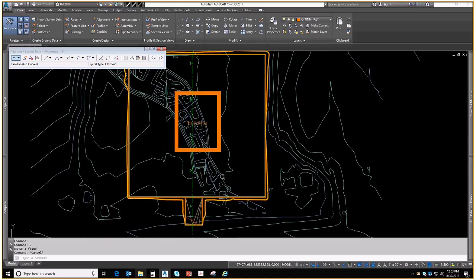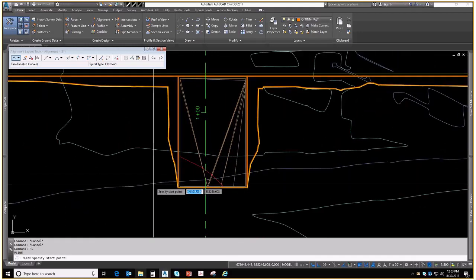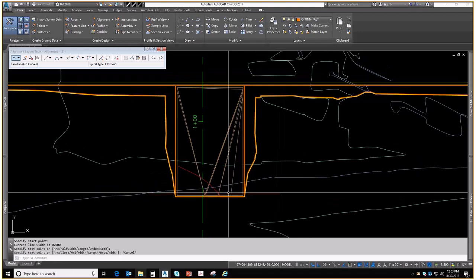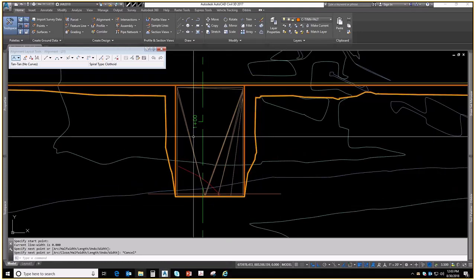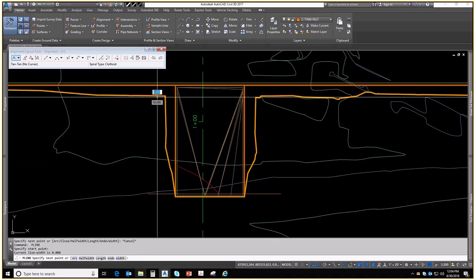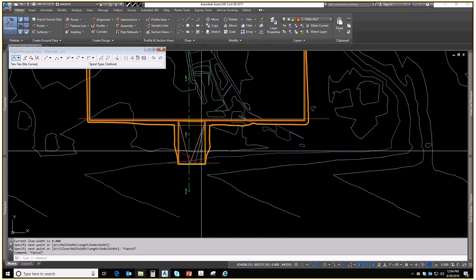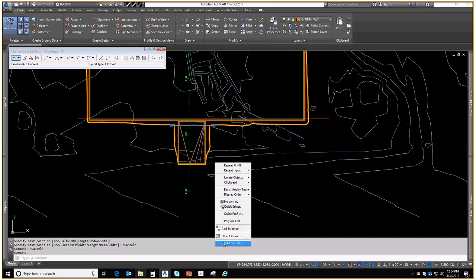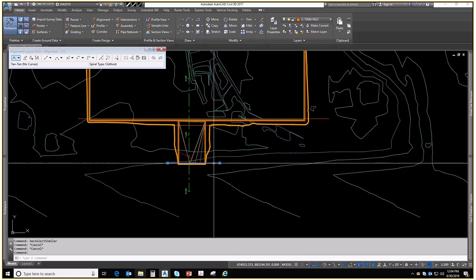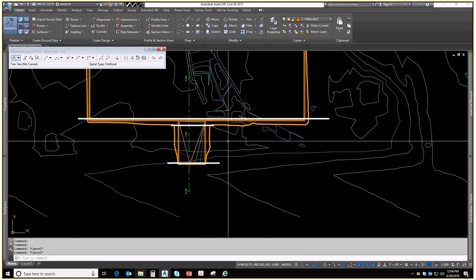So Joe, go down to the taxiway area and we'll talk about that a little bit. You obviously need a section at the very beginning of the project right there, and then in order to capture the transition in the slopes, you'll want another section right at the toe of the slope before you go into the apron, and then another section at the top of the slope where you go into the apron. You're looking at your horizontal design and plan, and making sure your cross sections are picking up transitions in plan from one area to another, and that will improve the accuracy of the average end area method. If you just blindly go in and put 100-foot sections or 50-foot sections without this level of refinement, you'll have some level of inaccuracy in your earthwork sections.